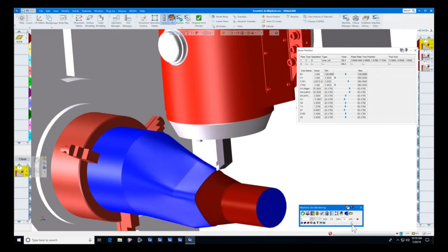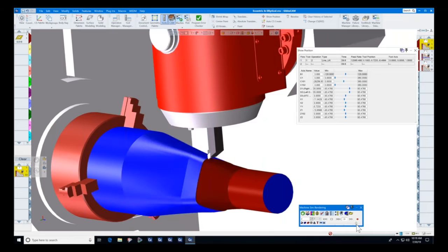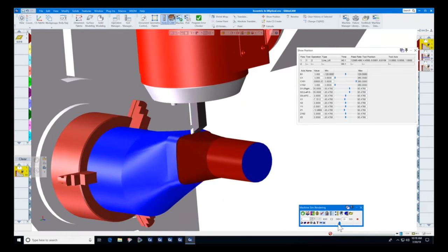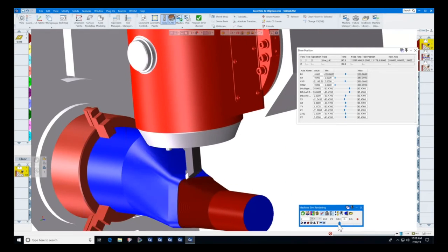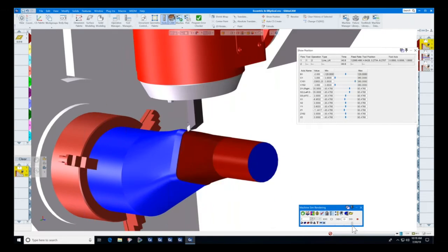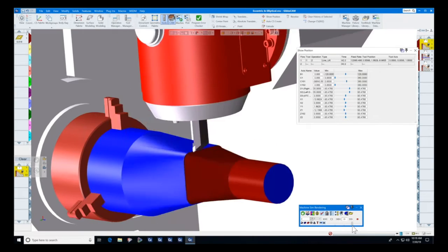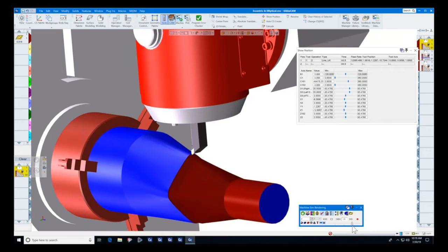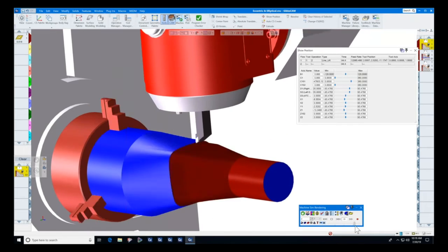We're going to move up the surface a little faster and watch it transition again from square. A lot of y-axis movement now. We're going to watch it now transition from square to round to finally concentric. So we can do all three types of toolpath on the same part. And yes, you can see we're going from square to round, so I'll speed this up a little bit.